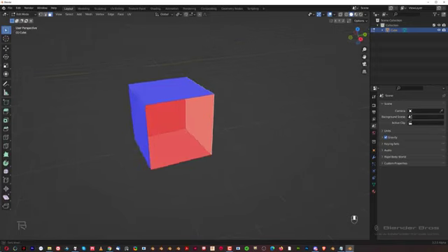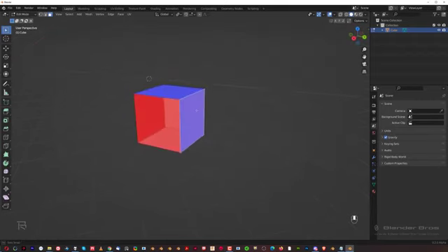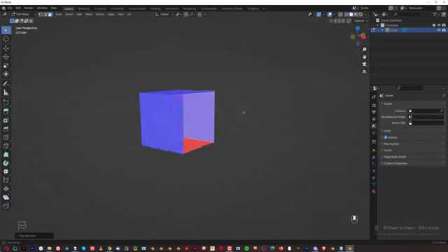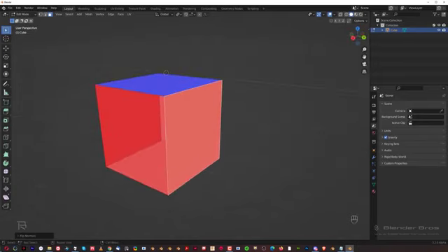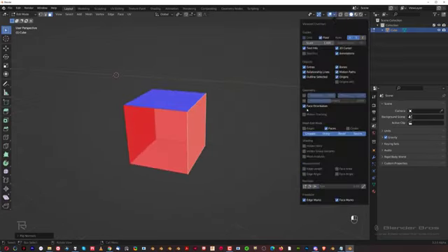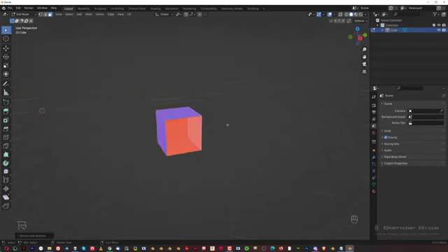So when you're modeling, occasionally it may happen that geo is flipped, which means it has flipped normals. So I press Alt N, and I simply go to this menu here and flip a face. You see now that the face is flipped. So if I, for example, want to run a bevel on that, it will not work that well, because the face is flipped. So this menu here will actually show you the face orientation, right? So let's select everything, Alt N, and we're going to flip it outside, which will flip this face back outside, okay?